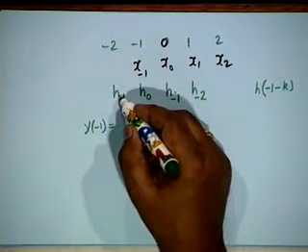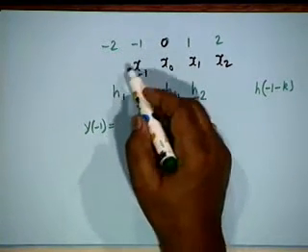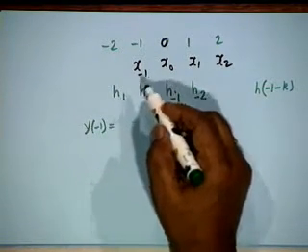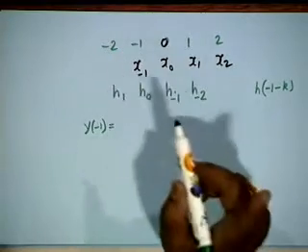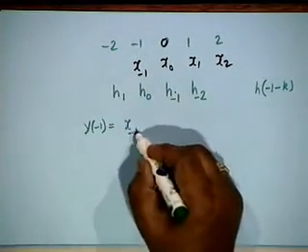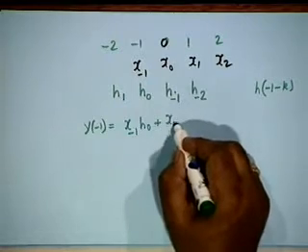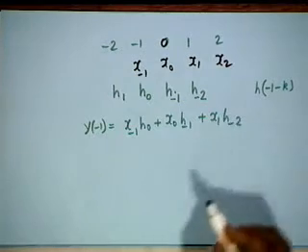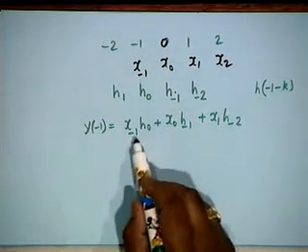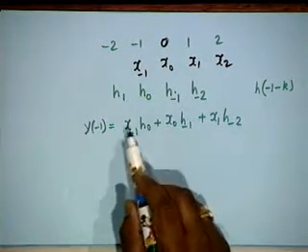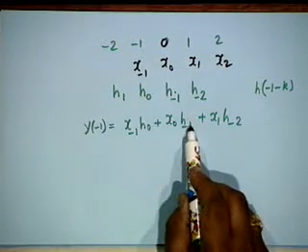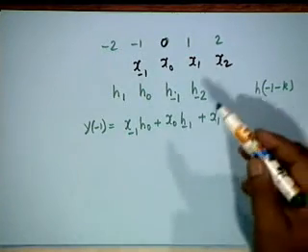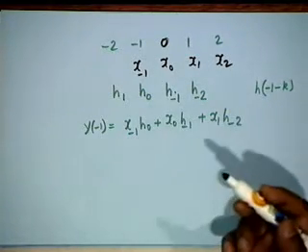this signal, there is no corresponding signal, there is no corresponding x. So, I did not have to write this, but anyway, since I have written, h1 multiplied by 0 is 0, then x of minus 1 h naught, x 0 h minus 1 plus x1 h minus 2. Again notice that 0 plus minus 1 is minus 1, this summation of subscript is minus 1, this also gives minus 1, and you can find out, compute all of them.